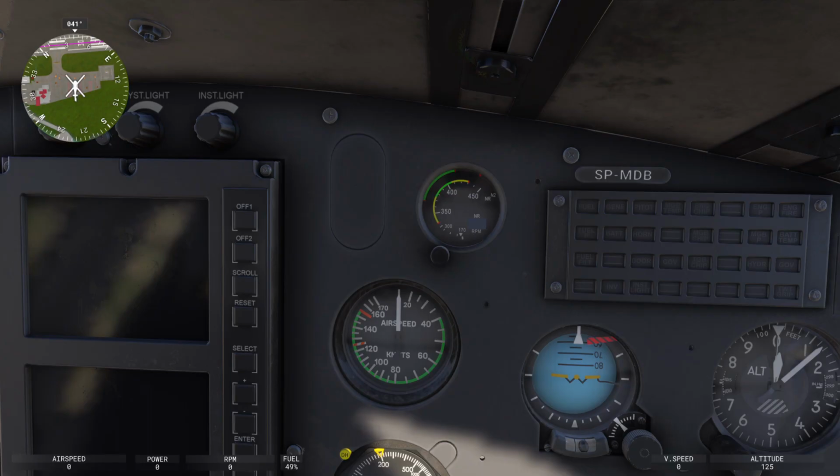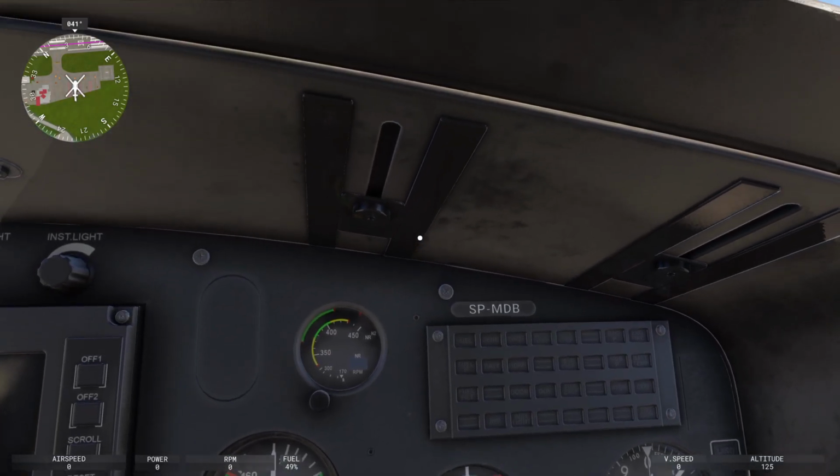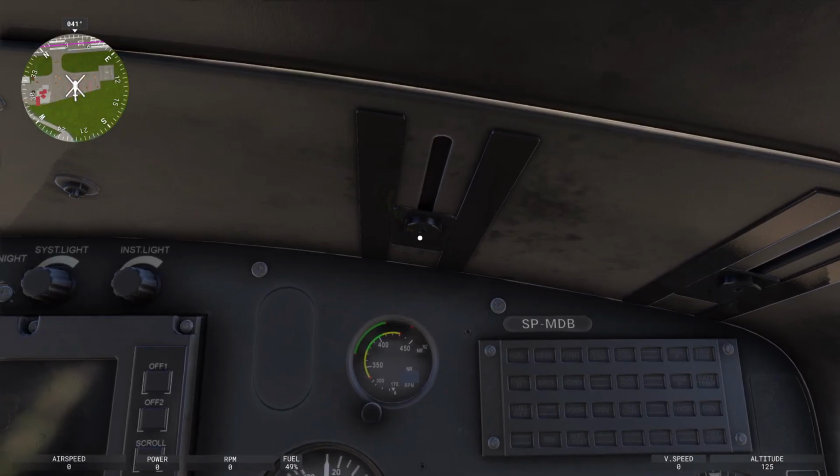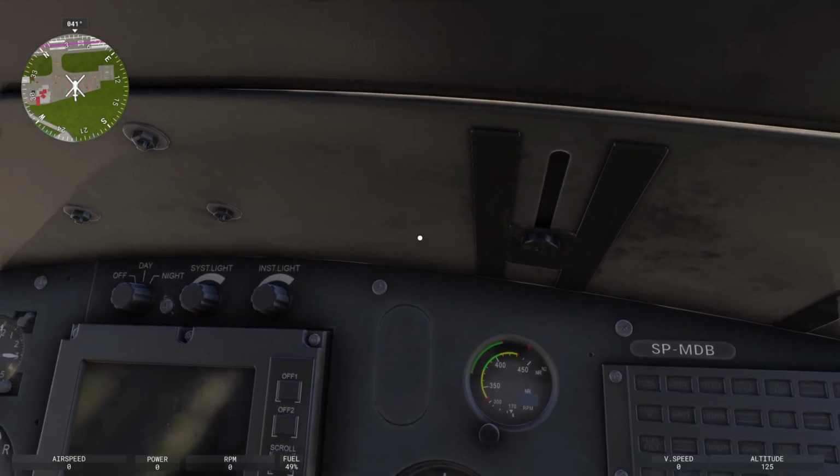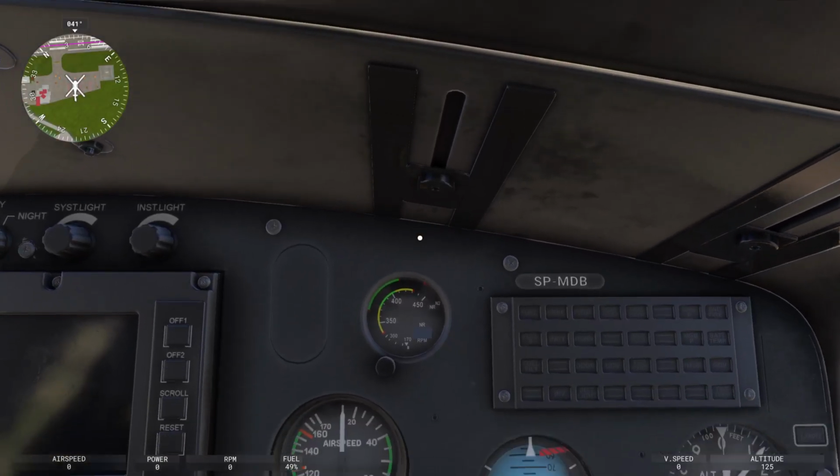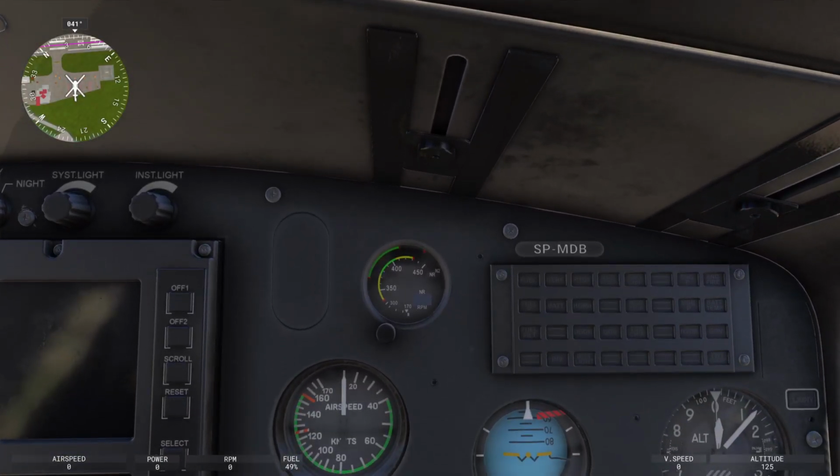You may have heard of a term called an auto rotation before. Now, I have tried it in this aircraft before and it didn't work, where I basically turned the engine off and I tried to land the thing. And the way you do that basically is you need to keep the airflow going through the head. So to do that, nose down, get some forward speed going. It just dropped me out of the sky. So it wasn't really designed. The sim hasn't been designed well enough to actually cope with that element of it. I don't think I've tried it on this helicopter. I think I tried it in a Cabri. It may work on here. We can try it a bit later on.